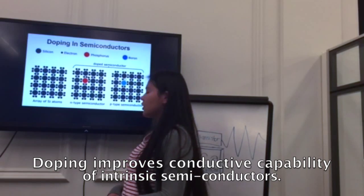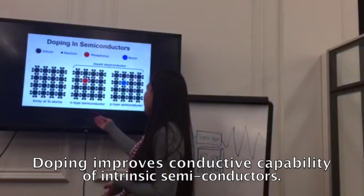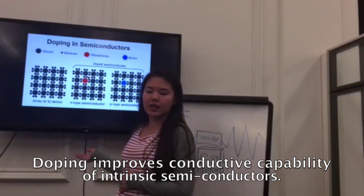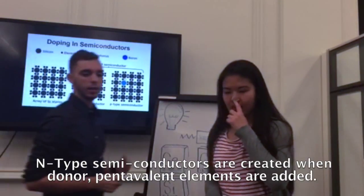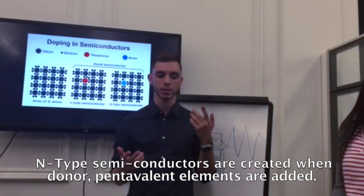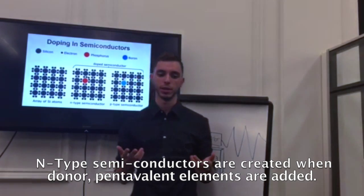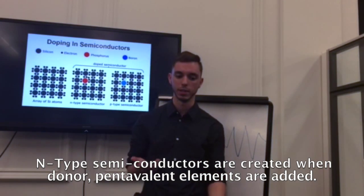Depending on the type of impurity atom added through a process called doping, an N-type semiconductor or a P-type semiconductor is created. An N-type semiconductor is created when a pentavalent element such as phosphorus, arsenic, or antimony is added. The extra electrons provided by these impurity atoms increase the conductivity of these semiconductors.